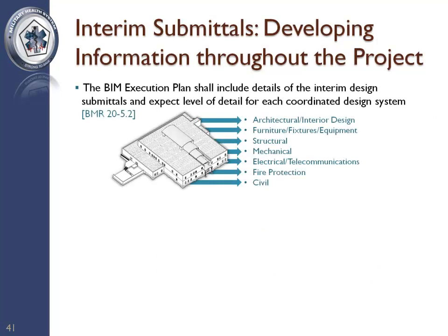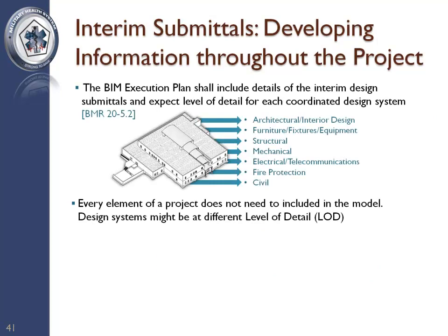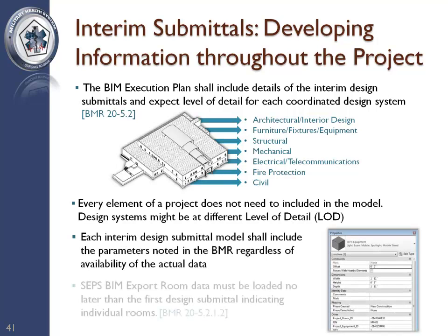Interim submittals should demonstrate progress toward project completion. Every element of a project does not need to be included in the model. It is important only to define the model components that are necessary to support each BIM use. BIM submittals should have the required parameters created even if the data to populate them is not yet available. The SEPS BIM export room data should be incorporated into the model no later than the first design submittal.